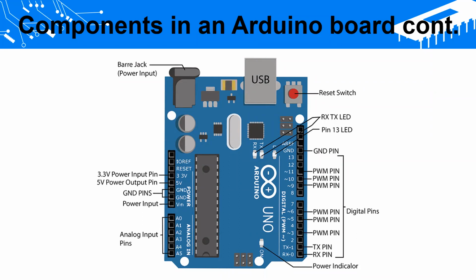Suppose you need to refer to a value like 10 volts, for example using some kind of high-voltage sensor whose output will be 10 volts or so. With these analog pins, you are capped at 5 volts, so the maximum voltage you can sense is 5 volts. But in this scenario the sensor gives an output like 10 volts. Suppose the Arduino board won't burn; in that case, you can use this AREF pin.